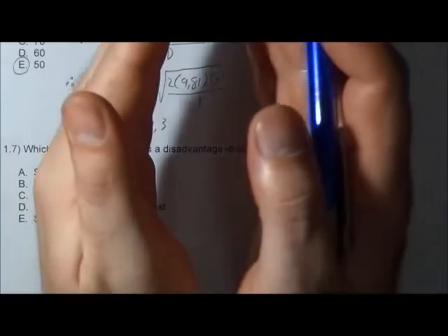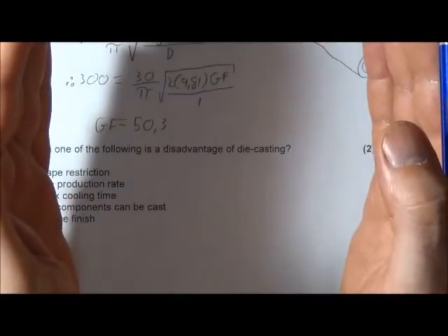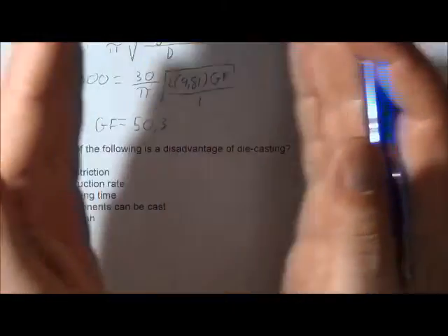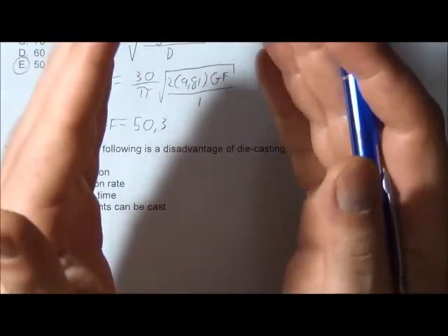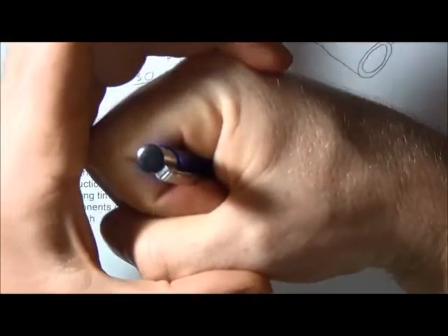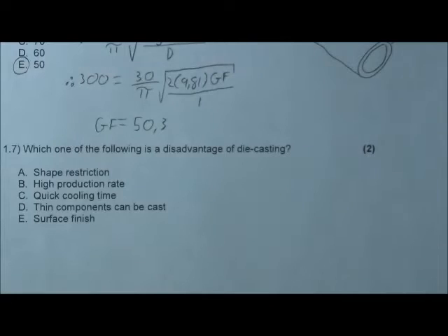So these two molds come together, material is injected, and then the molds split apart again. So something to remember with this splitting apart of the molds, it has to be such that you cannot have any hugging around of the mold. If it hugs around the part, you won't be able to split the mold again.